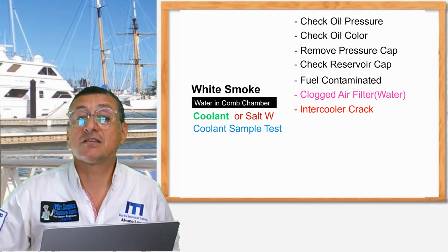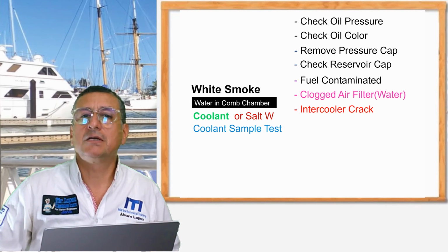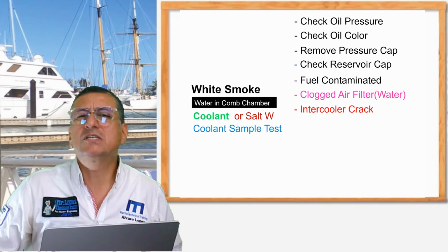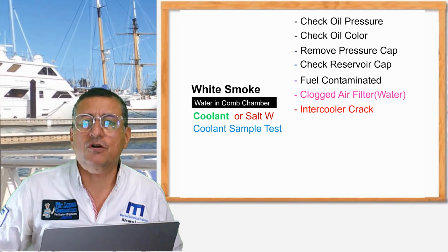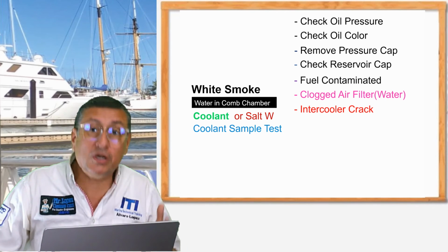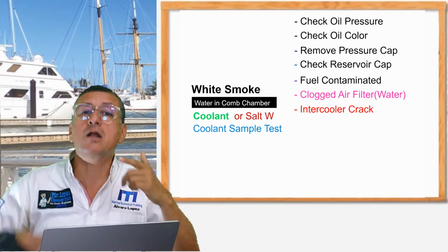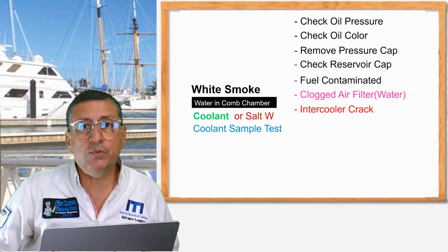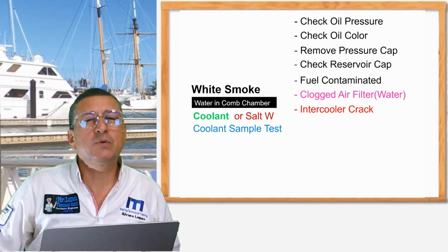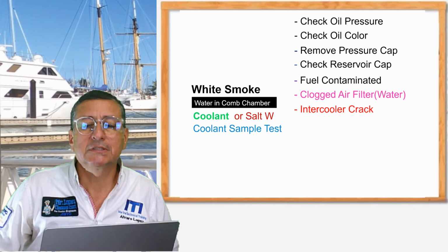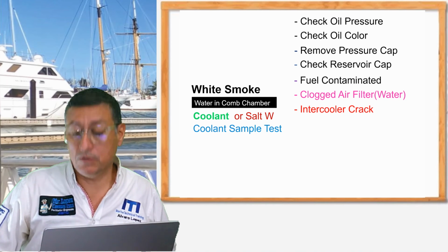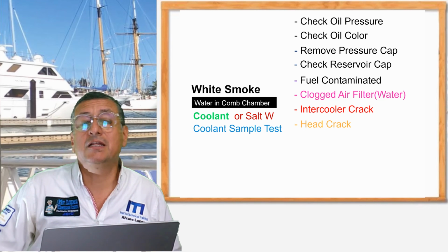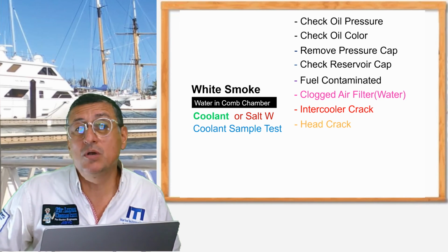It locks because of the thermal expansion of dissimilar metals that occurs at the moment of the explosion with salt water. With salt water, the situation is catastrophic. With coolant, it's also catastrophic, but the engine can run. You can recover the engine easily if the problem is with the coolant. If the problem is with salt water, it's difficult. Okay, another possibility for water entering the combustion chamber, in that case the coolant, is a problem in the head.